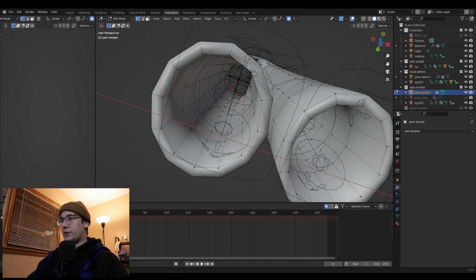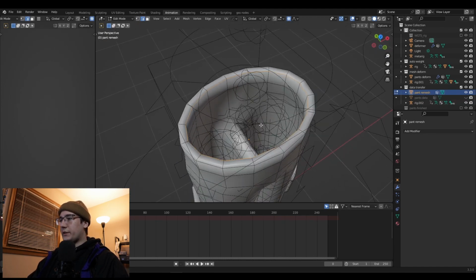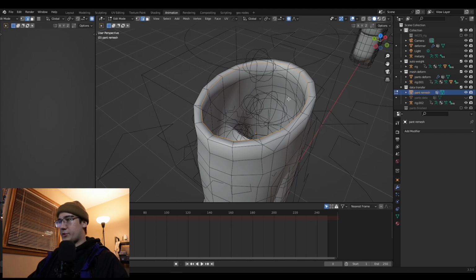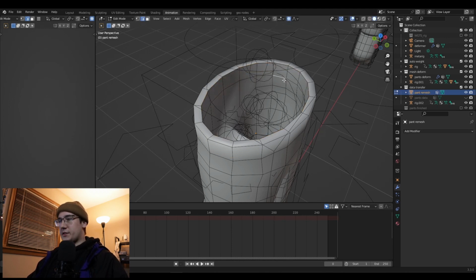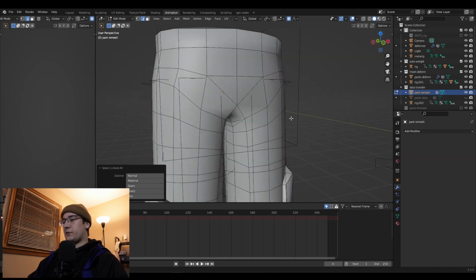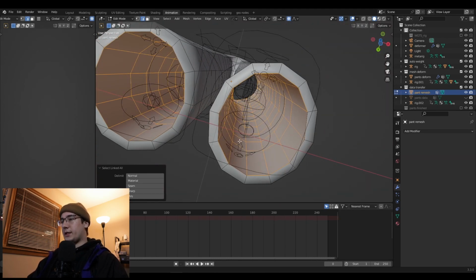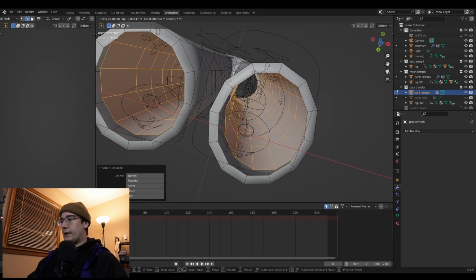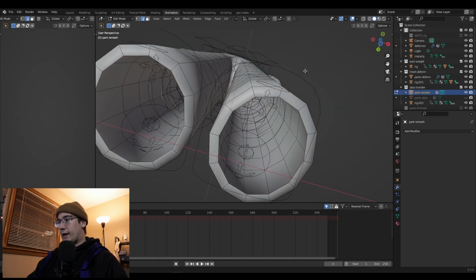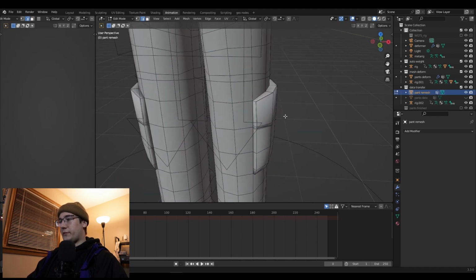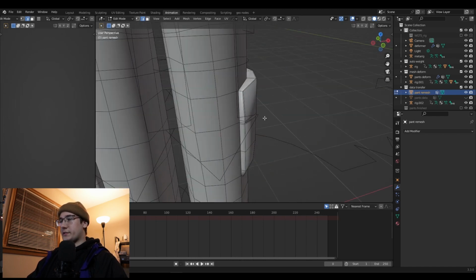and first thing I'm going to do is select these loops on the interior, and I'm just going to hit V so that it separates those edge loops into their own thing. And now this interior piece, if I select anything in here and hit Control L, it is going to select everything in here that's connected, but now they're not connected anymore because we already ripped them apart. And I'm just going to delete that so our remesh modifier doesn't get confused when we have interior faces.